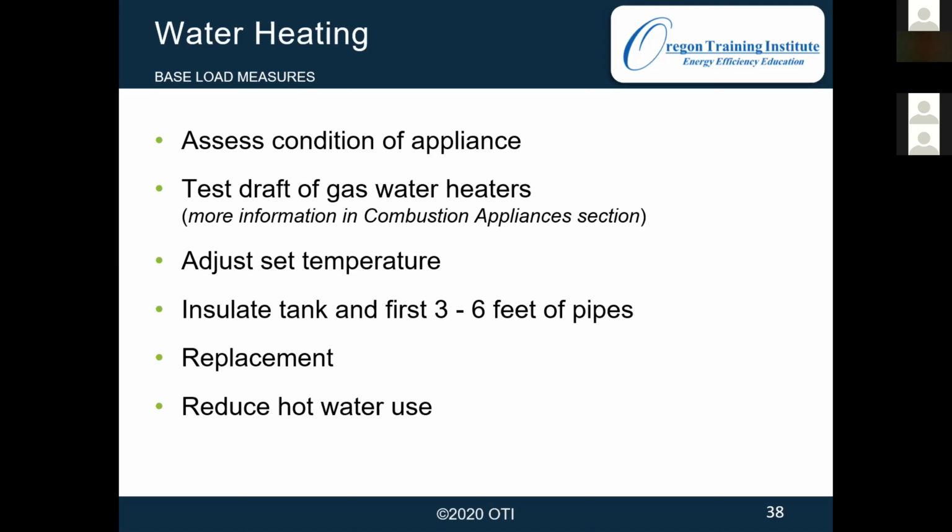At 120 degrees, it's going to take over 5 minutes for that water to burn, whereas at 140, I think it's like a minute. At 160 it's like 5 seconds before it causes a third-degree burn. So very high. The higher the temperature, the higher the burn risk.